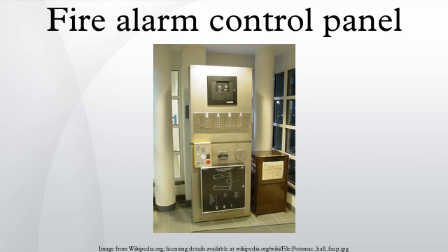When held steady or flashing, it means that a trouble condition exists on the panel. Trouble conditions are often activated by a contaminated smoke detector or an electrical problem within the system. Trouble conditions are also activated by a zone being disabled, a circuit being disabled, low power on the backup battery, the disabling of a notification appliance, ground faults, or short or open circuits. Usually the alarm panel sounder will activate if a trouble condition exists, though older systems would sometimes activate a bell or other audible signal connected to the panel.